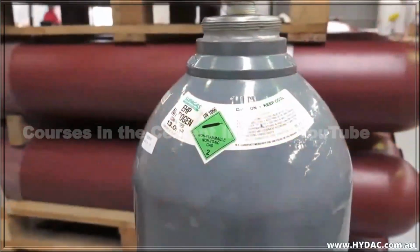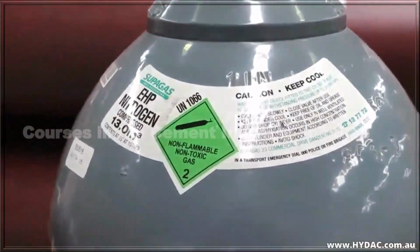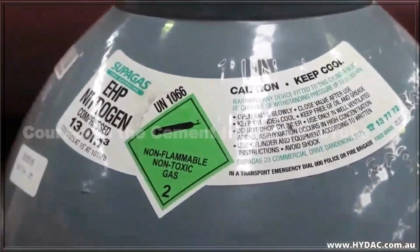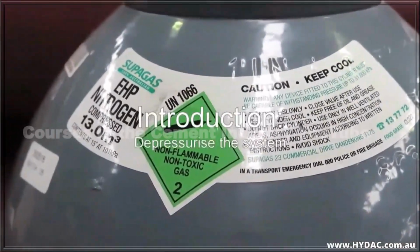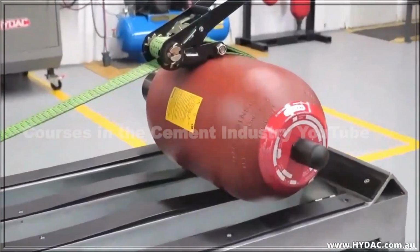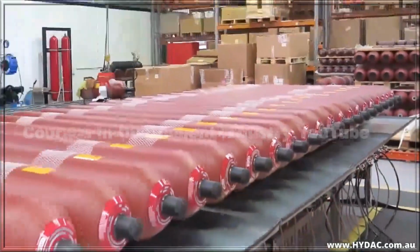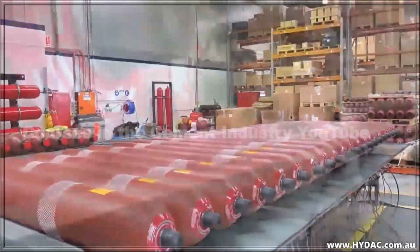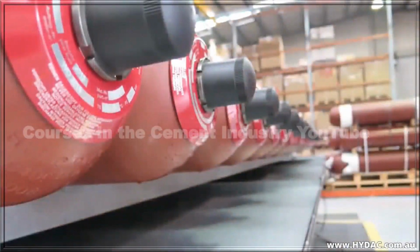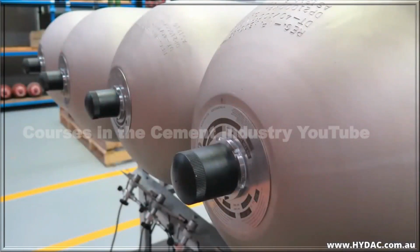The nitrogen pre-charge pressure of an accumulator can only be assessed when it has been fully depressurized of hydraulic fluid. This means that the accumulator must be positively isolated from a live system and released of all hydraulic energy, or that the entire system has been completely shut down and fully depressurized, or that the accumulator is not currently connected to the system. For example, it is on a workbench.